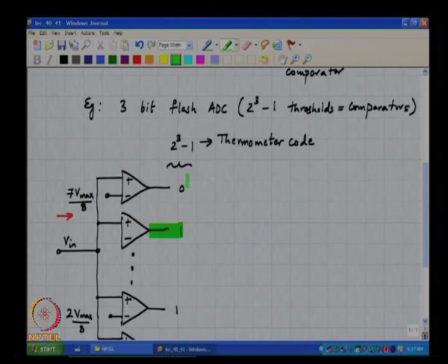So in principle what you really care about is the transition between the all ones and the all zeros, and all the comparators above this one and all the comparators below this one are basically redundant as far as figuring out what the input is. You understand? So that explains why a flash converter is fast, and also explains why it is, within quotes, very wasteful of hardware. So it is naturally only used in applications where A, latency is paramount, and B, where the hardware complexity is modest.